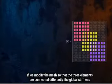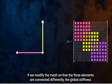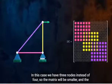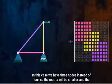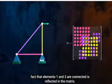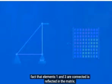If we modify the mesh so that the three elements are connected differently, the global stiffness matrix will change. In this case, we have 3 nodes instead of 4, so the matrix will be smaller, and the fact that elements 1 and 3 are connected is reflected in the matrix.